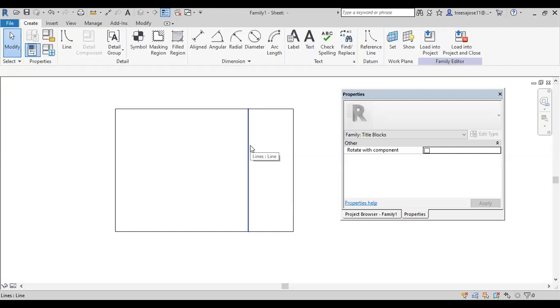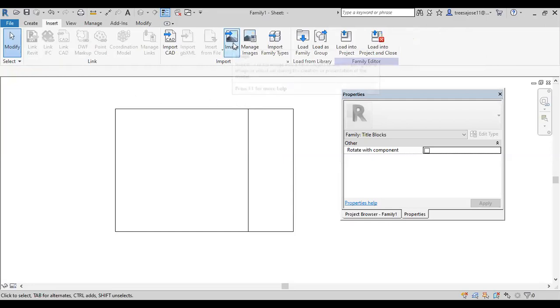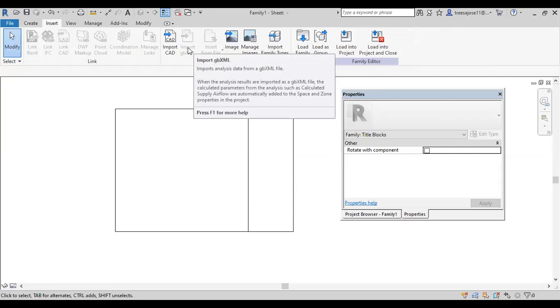Sometimes we have to add the logo of our company and all. That time you go to the insert tab, import image. In the case of submission, the septic tank details and all are there; you can add that into this template also. That will be in those particular positions. Or you can draft with the help of drafting view also and insert it. I think it is better in the case of submissions, where the rainwater percolation pit and septic tank are the same, to insert that in the template itself, so our work will be much easier. Okay, that depends upon us.